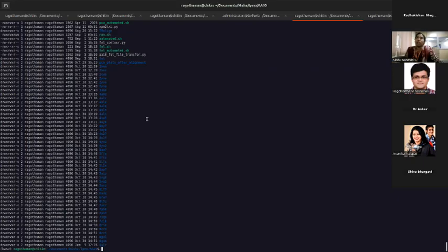So to ensure that all the steps are taken care of and there are no errors getting in, and sometimes you have to tune the steps also. For example, for some proteins you should add greater charges, for some other proteins you should add fewer charges. Let's take the example that I showed you before. I had a protein where the loop is out of the box. In those conditions, if I visualize it before simulation, I can change the box size and make the water molecules fill the entire box. Otherwise the simulation will run, and at the end of it I'll notice that and it will be a waste of computation. So it is always suggested to manually visualize all the preparation steps.